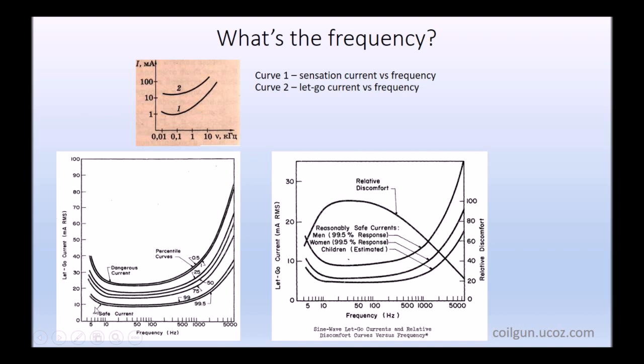Another reason why we cannot take the frequency too low is that in real conditions, fight conditions, the contact of our shocker to the object's body cannot be in a range of seconds. It is only maybe a part of a second or half a second. And during this period, a few pulses should run through the body to have some effect. So the frequency cannot be 1 Hz or 2 Hz, for example. It should be 10 Hz, and then in real models it begins from maybe 20 Hz.